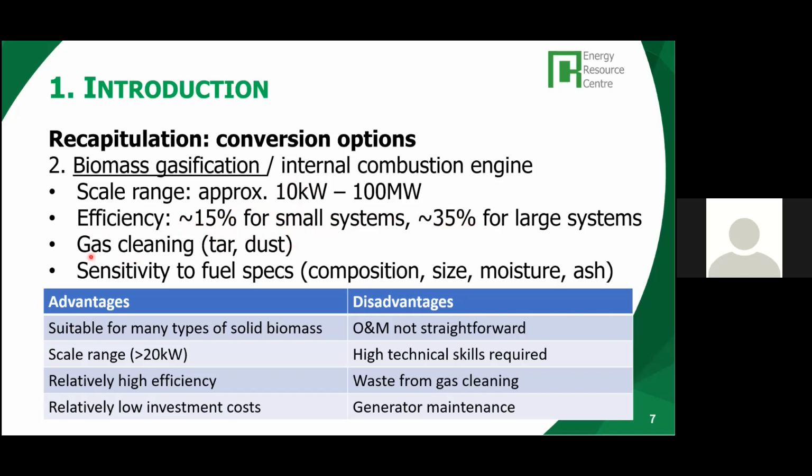Critical points are gas cleaning, making sure that the producer gas is free of tar and dust in order to avoid any damage to the engine in which the gas is used. And the technology is very sensitive to the specification of fuel, particularly size, morphology, moisture content, the ash content, and, say, the overall composition, the mixing of different types of biomass.